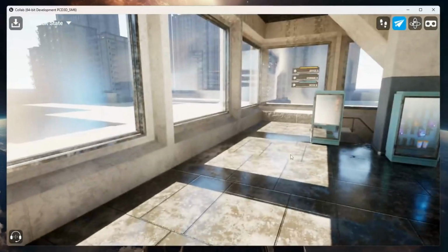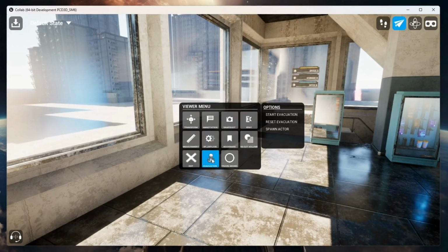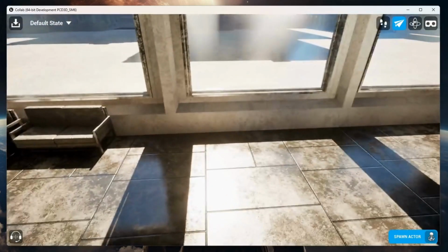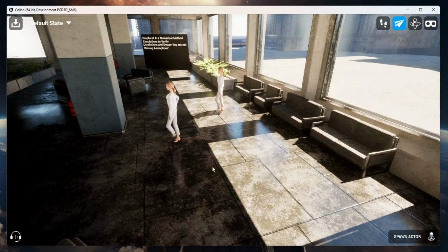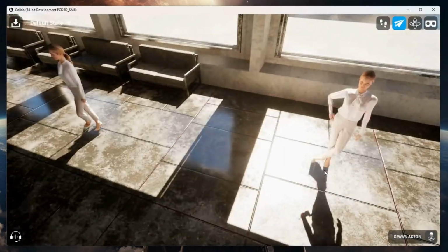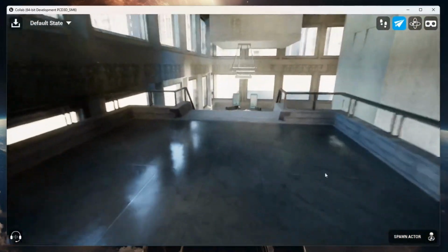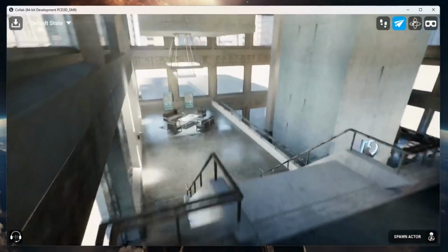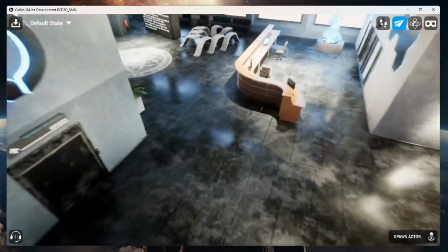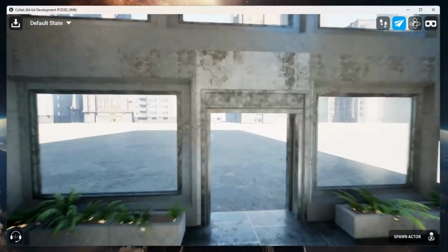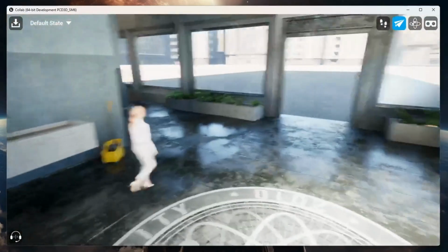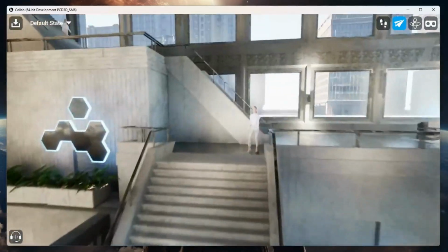But we can also do a more accurate or a more complex simulation. So let's say for this building, you have to do a means of egress evaluation. You do your evaluation, but it's kind of hard to explain to people what's going on. So I can write a program, or we can write a program, that allows you to put people wherever you want. And then you can set a muster point. I have a preset muster point in this case, which is that little white slab. And then I press the start evacuation. And all those people that we spawn will start walking to the muster point.